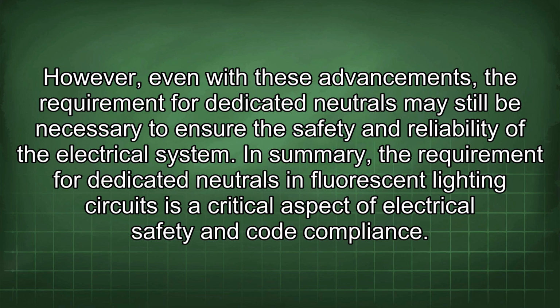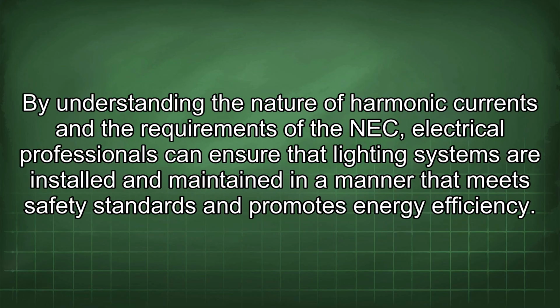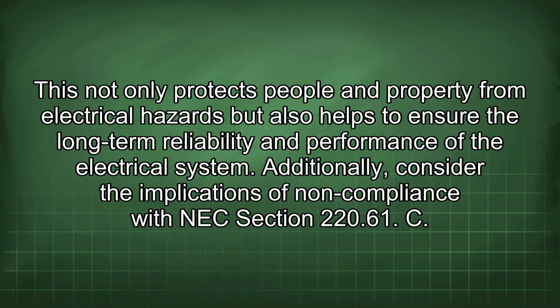In summary, the requirement for dedicated neutrals in fluorescent lighting circuits is a critical aspect of electrical safety and code compliance. By understanding the nature of harmonic currents and the requirements of the NEC, electrical professionals can ensure that lighting systems are installed and maintained in a manner that meets safety standards and promotes energy efficiency. This not only protects people and property from electrical hazards, but also helps to ensure the long-term reliability and performance of the electrical system. Additionally, consider the implications of non-compliance with NEC Section 220.61.